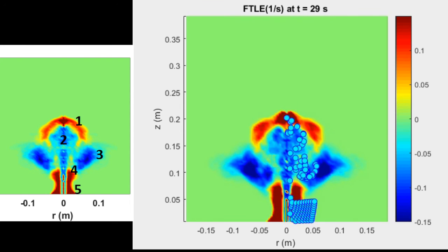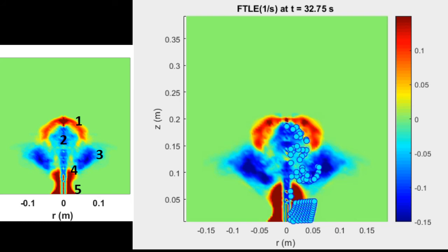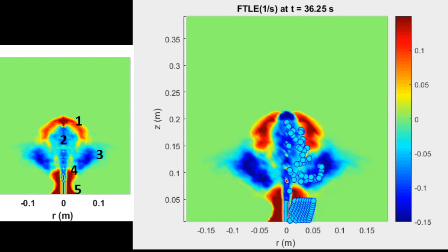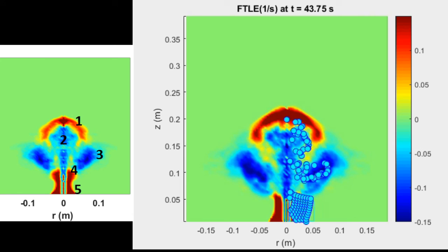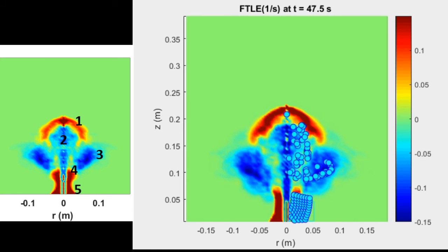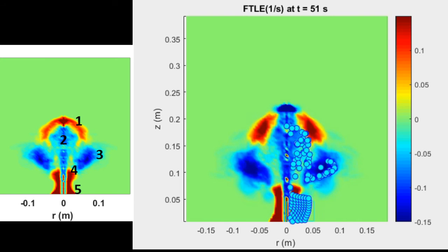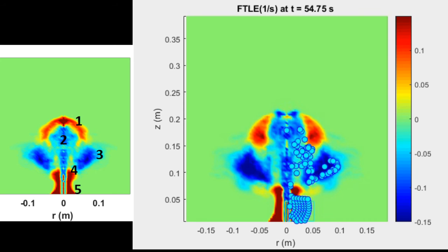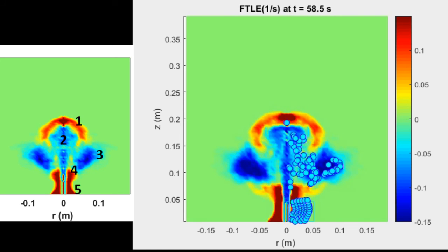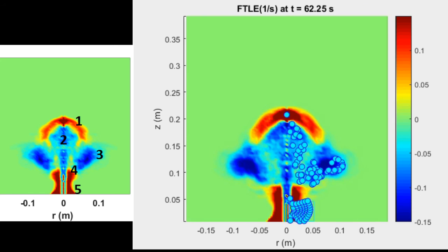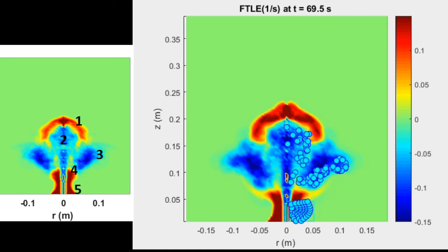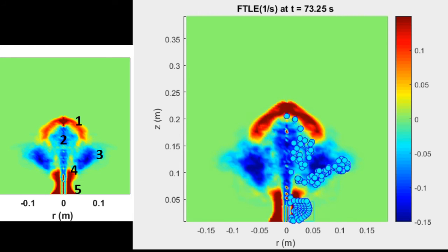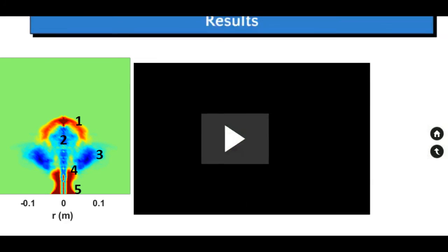This structure is responsible of 1. The entrainment of fluid from the surroundings, and 2. The entrainment of fluid into the upward jet, which is mostly re-entrainment. The third LCS is located around the spreading height and leads the flow radially away from the fountain axis. The fourth LCS prevents the spreading flow to fall beyond the spreading height. And the fifth LCS limits the edge of the jet and is sometimes connected to the fourth LCS.